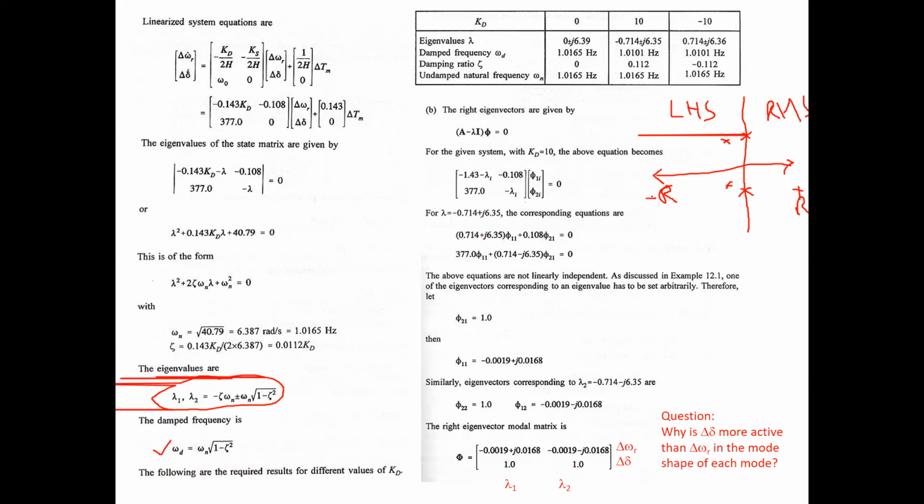This is minus here, and this is plus. Okay. So if you have negated the load damping constant, it means that the eigenvalues are located on the right hand side here. And if you have them on the right hand side, and again, what you see, the damping ratio, what is the sign here? It is minus. So it means that